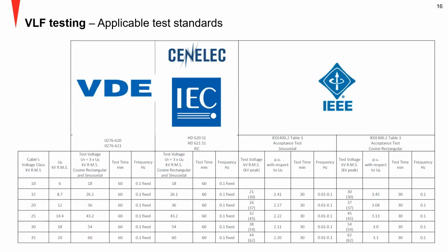And then I want to point out a difference here, which is significant in practical testing. IEEE is diverting from the commonly established IEC test practice. As you can see, the values are given as a function of the waveform, which is not the case in IEC. I will get to this in a second. Frequency reduction is allowed as a loophole. Testing time is a little different, and specifically the test values are very different from the IEC test values.